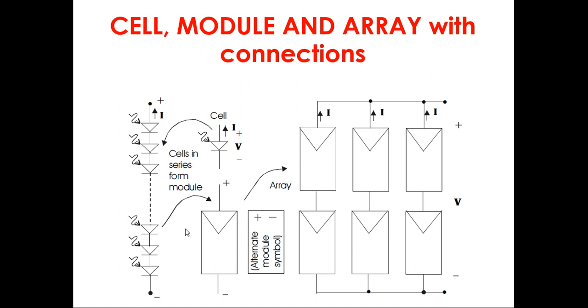In this case we have 60 watt each, so 120 watt. Likewise, two more strings, total 3, will generate 360 watt of power. But the voltage and current depend upon the series and parallel connection of the modules, and it is decided by the connection of the inverter for the grid tied system, or else by the battery rating for standalone applications.